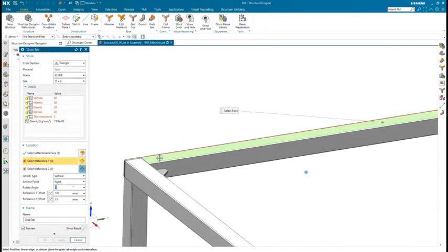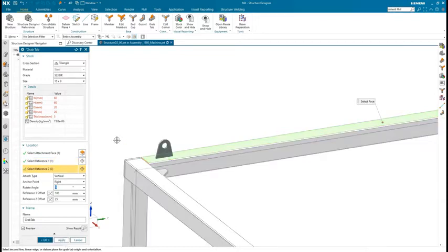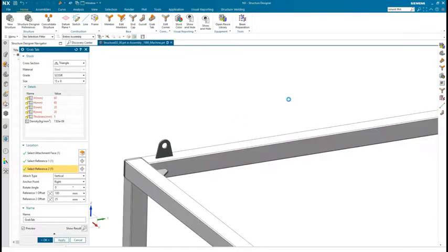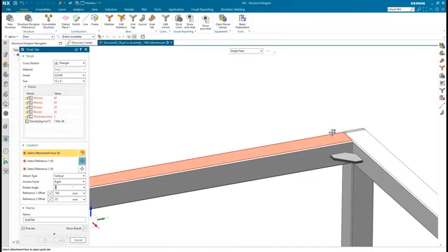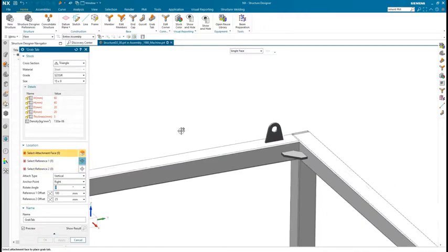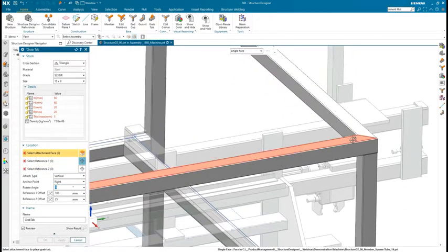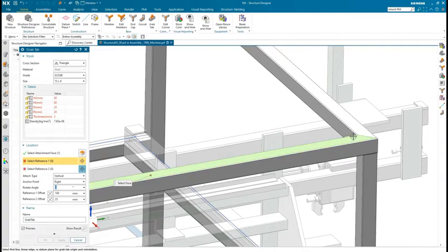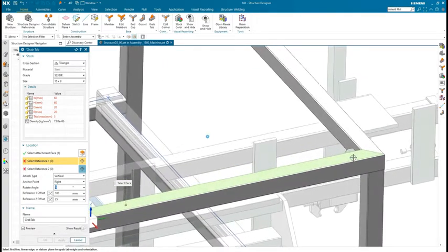To simplify transport of this machine to its final destination, we'll add some hoist tabs. Adding them is a similar process like gussets. Choose the shape, enter the size, and select the location. The tab shape can be triangular, rectangular, semicircle, or trapezoidal. We'll add a total of 4 to the top rails.